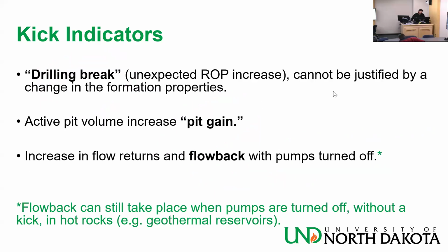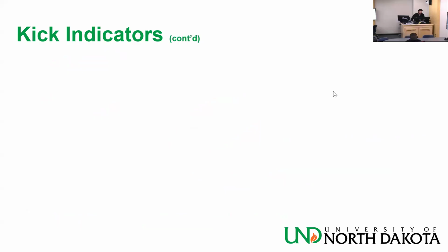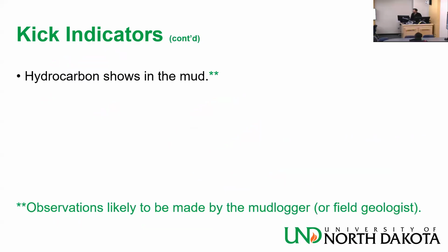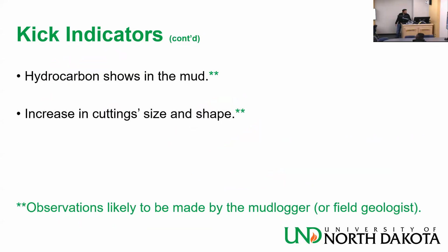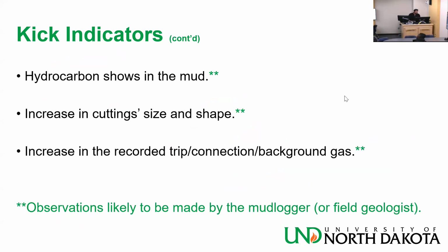So these are some indicators. Let's see some other indicators. Hydrocarbon shows in the mud. Increase of the cutting size and shape, they become noticeably bigger. Increase in the recorded trip, connection, and background gas. All the gas readings go up.